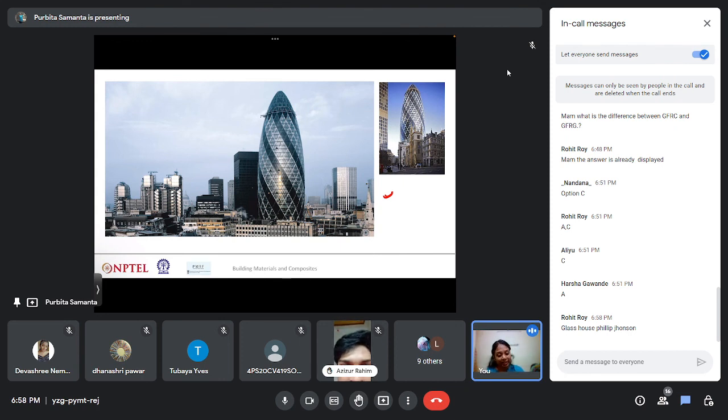But very interestingly, not a single piece is made of curved glass except the very top one. That is just one particular glass that is curved. All the other glasses that have been used are straight, non-curved glasses, and that was possible only because of this diagrid framework.